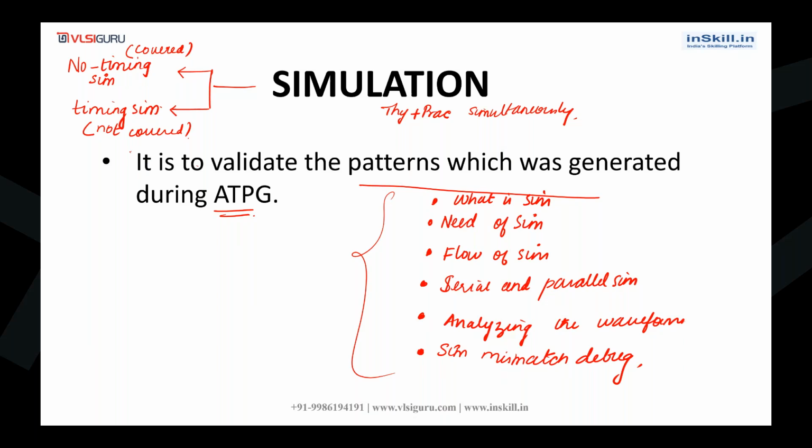The reason is, in order to do timing simulations, we require a file called an SDF file, standard delay format. The SDF file is not available for the test case which is there in our institute. So that's why in the DFT course, we will be covering only no timing simulations.